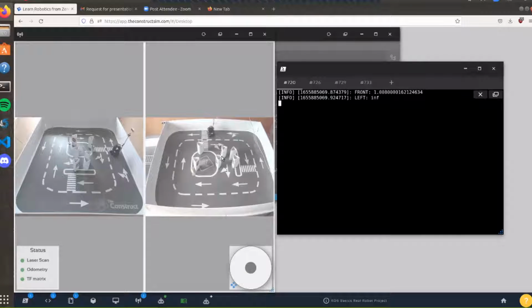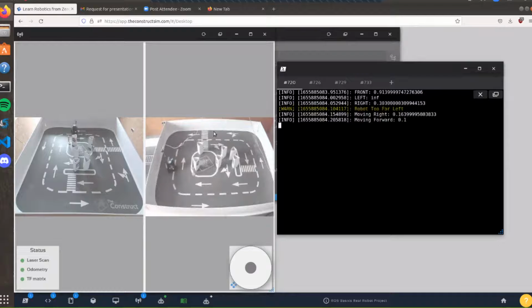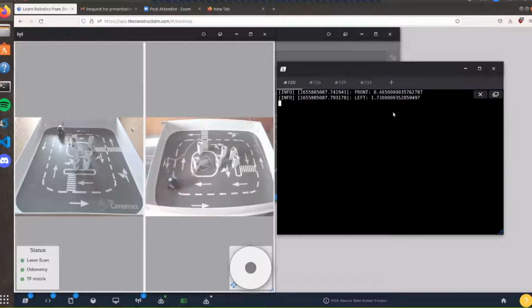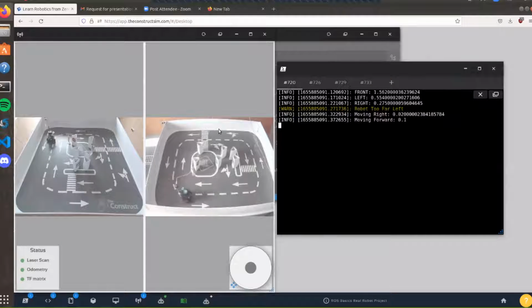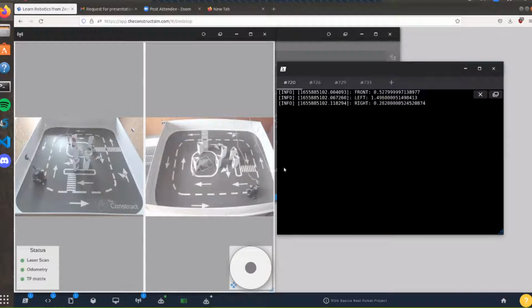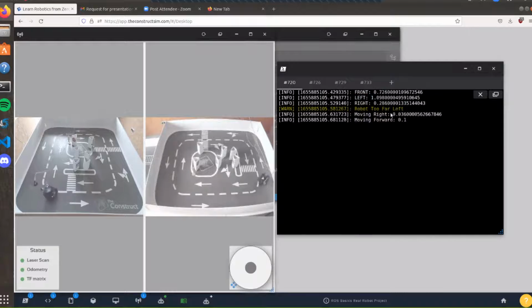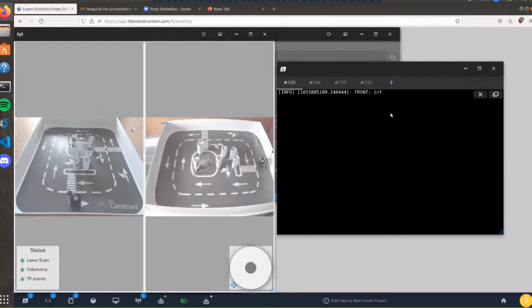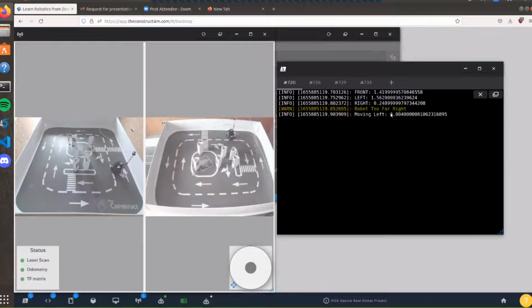Okay, it was a bit fast, but first he called the service to find the wall. I put him next to the wall, so he just starts checking what is the minimum distance that I have, and then he sees if he should go right or left depending on the index of the closest ray of the laser. And then it starts turning. It then starts going forward until it's about 30 centimeters from the wall, and then it turns left so it can face the proper direction.